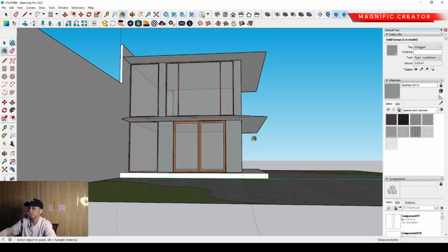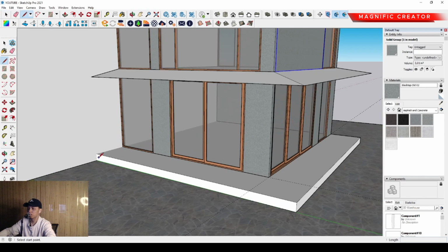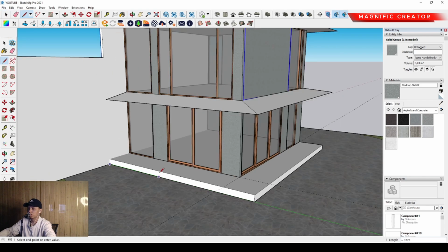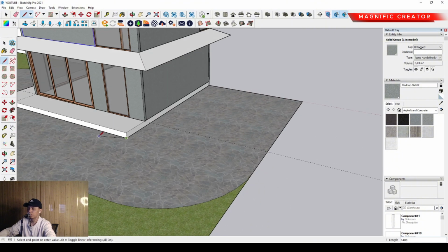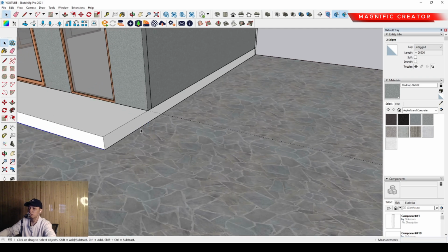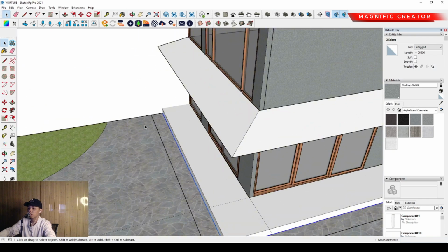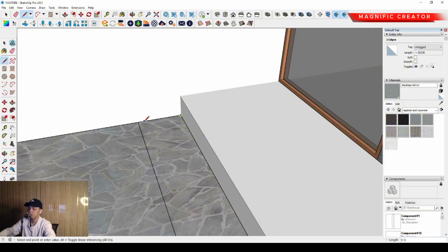Okay, this is about another exterior look for the Japanese model. We can make another floor terrace area in this position. Then we can offset it outside around 400 millimeters only, or maybe more. We can offset it inside around 600, just like this. Then we can complete the uncompleted line over there. Okay, we can use it.